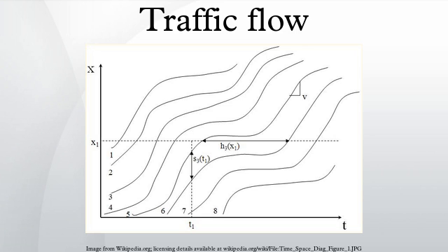The probability of traffic breakdown is an increasing flow rate function. There is a well-known hysteresis phenomenon associated with traffic breakdown, when the breakdown has occurred at some flow rates with resulting congested pattern formation upstream of the bottleneck. Then a return transition to free flow at the bottleneck is usually observed at considerably smaller flow rates.